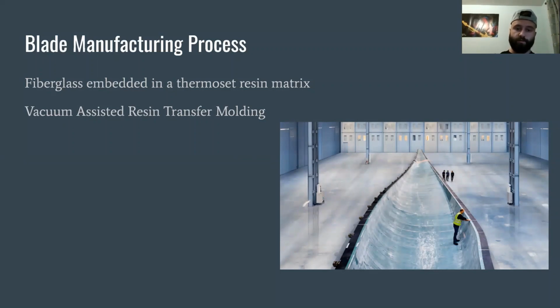The gel coat is an epoxy-based thermosetting coat that provides a finish for the blades and facilitates the removal from the mold. Fiberglass weaves are then rolled into place to smoothly cover the mold surface. Towards the base, balsa wood or polymer foam are sandwiched in between the fiberglass layers to ensure greater structural integrity.